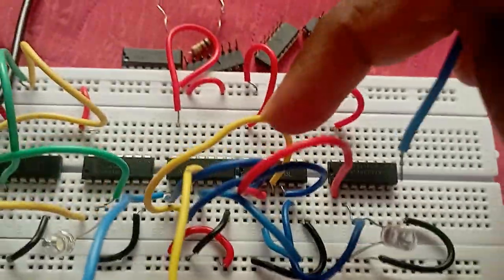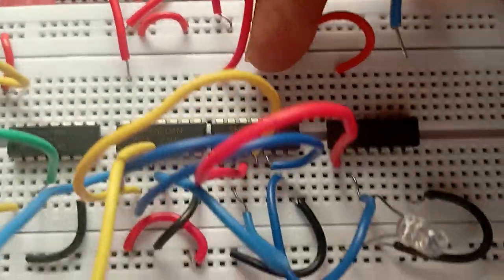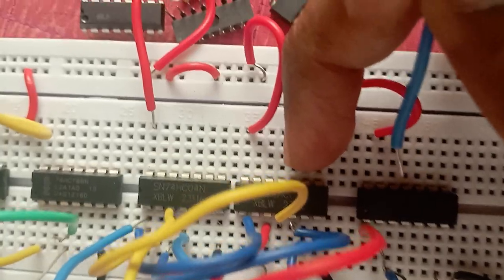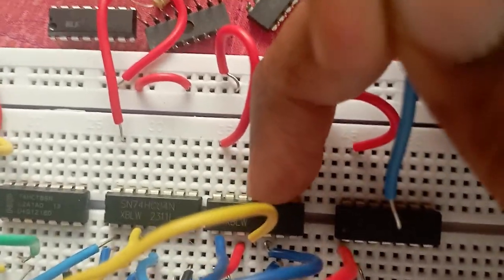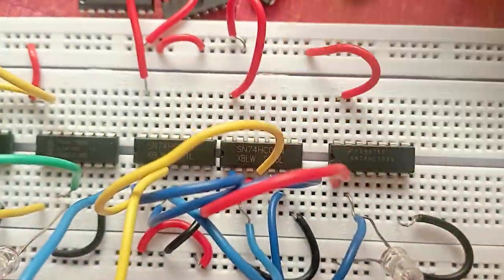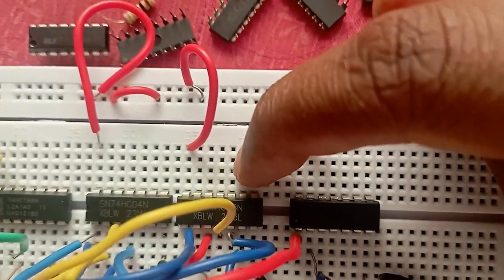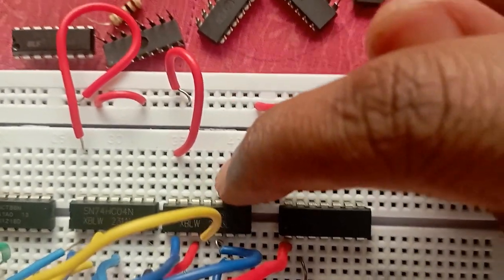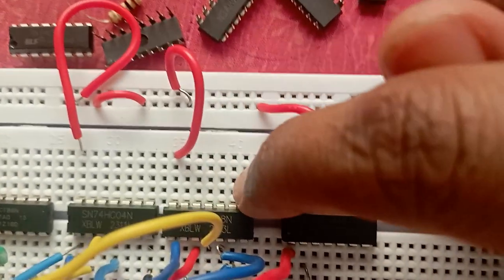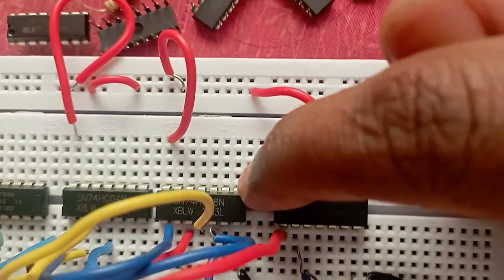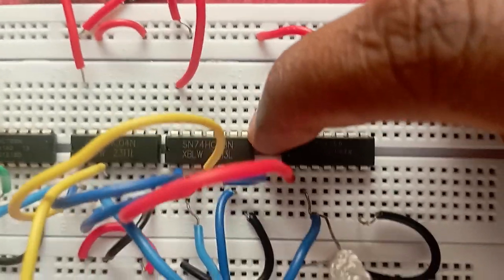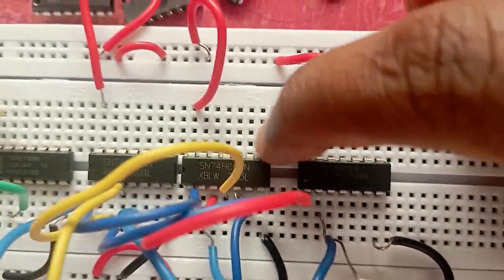So we have used the two AND gates of this side. I am going to use one AND gate of this side. So I am going to use the pin numbers. So these pin numbers are 8, 9, 10, 11. At the upper side the AND gate is in this position. So input has to be given at the place of pin numbers 10 and 11. 10 and 11 are going to be inputs, and 9 is going to be the output. So we are going to connect the LED at this place.